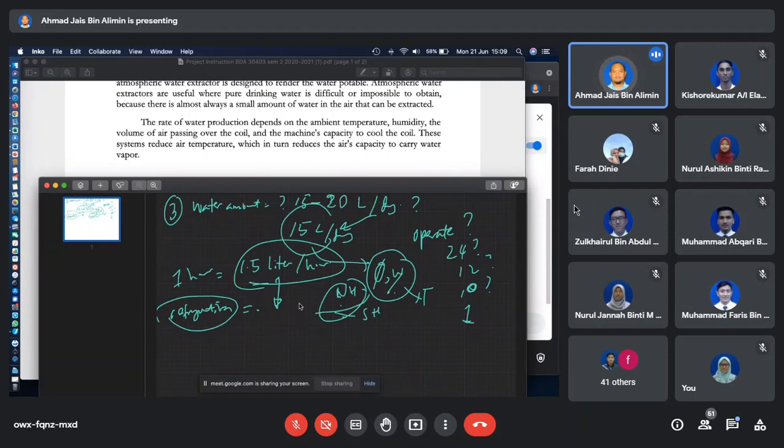If you are trying to extract the water from the environment, that's why in the chapter on mixtures we have the dew point temperature concept. You have the refrigeration, and you have the dew point. You want to push the air to reach the dew point temperature, so you have to configure how you're going to achieve dew point temperature at a certain stage of the air flow rate, because your feedstock, your input to the system, is the surrounding air.